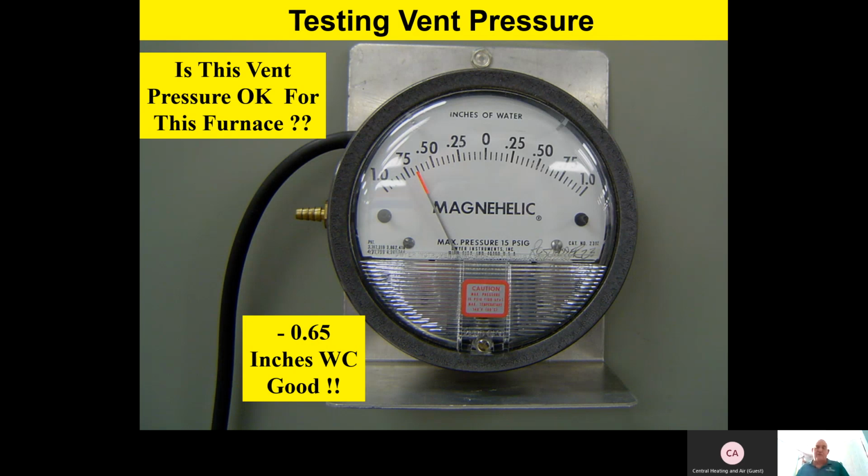Now I've seen some of our furnaces with really short vent pipe and very few elbows in the vent pipe close that pressure switch at a particular value. In our example, a 0.5 is where it closes, but I've seen it sucking down almost 1.0 inches of water column.